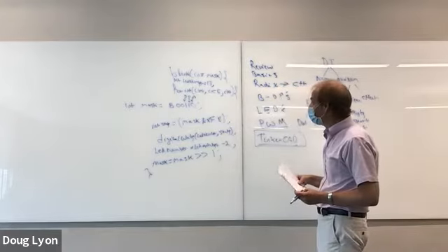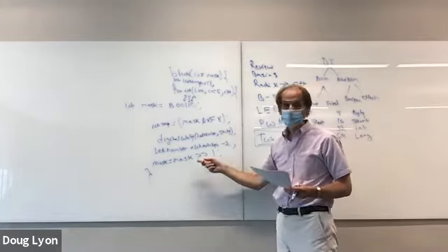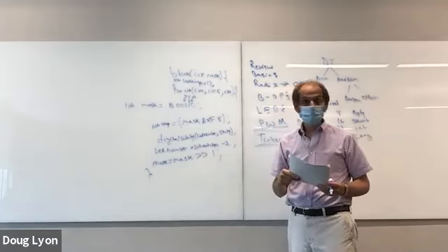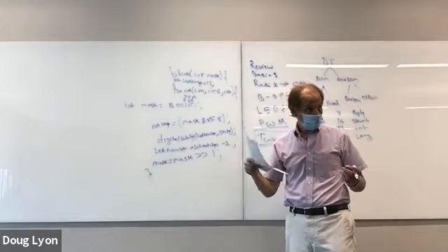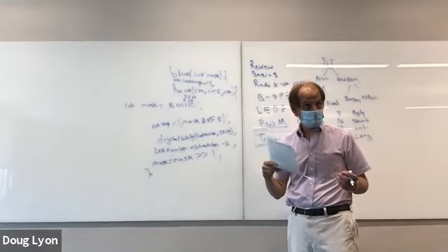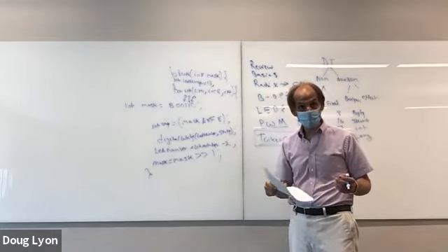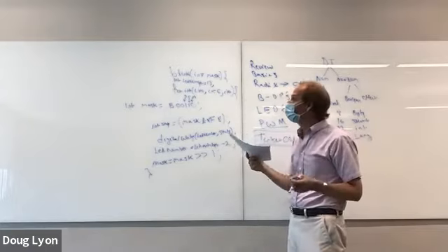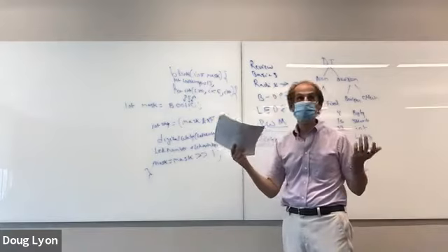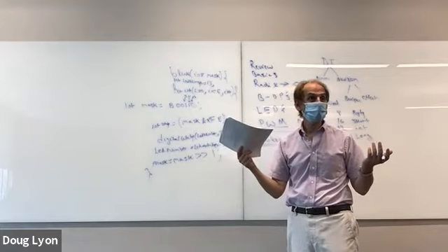And we already know we can shift the mask to the left when we are encoding, so we can write out a for loop for encoding. Put a 1 in there, shift it to the left, shift to the left, and we're done. Shift to the right, shift to the right, and then we proceed to write the mask out each time to the blink.